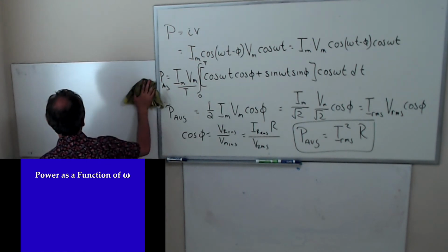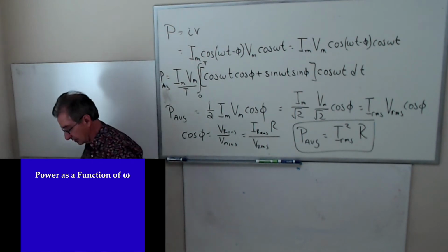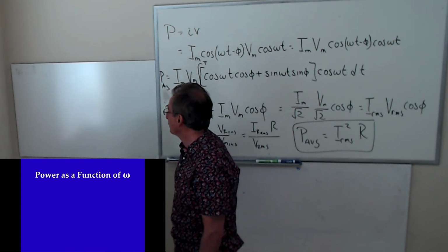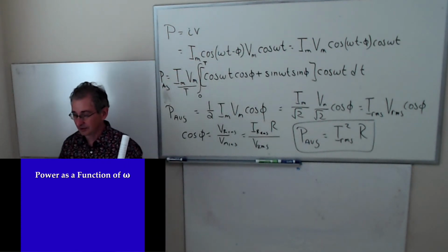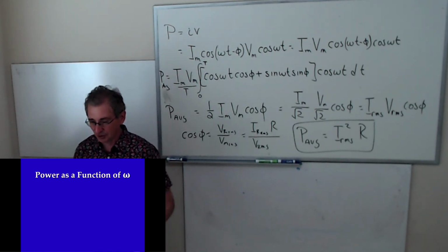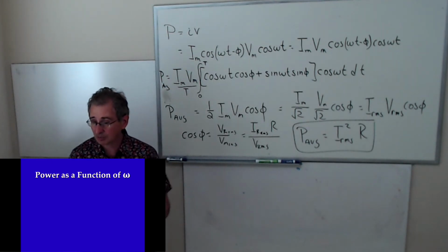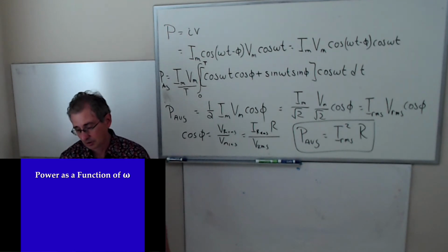Is the reason because the resistor is always in phase with the power supply? Yeah, you can say it that way. You can couch it that way. You can say it a different way when you analyze it in terms of complex exponentials, because the resistance is always treated as something real. And I think what you said is perfect, and might be better. But when you talk about how the capacitor and the inductor behave, they're always treated like an imaginary number. And so they're actually completely separate. And it really is because of the fact that the current through the resistor is in phase with the voltage across the resistor.